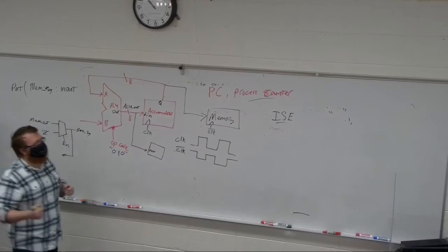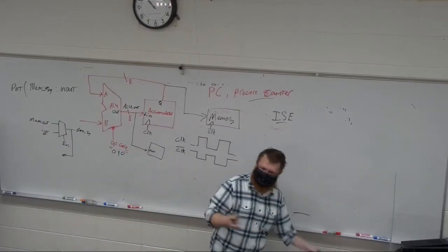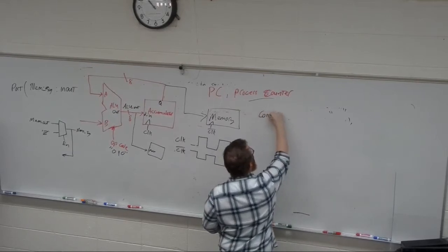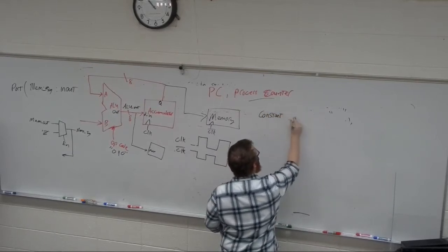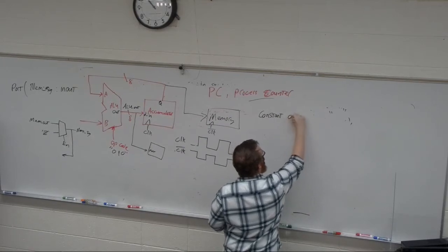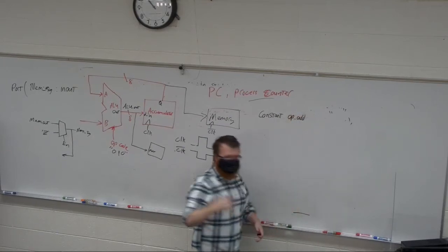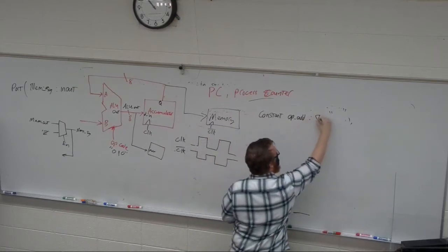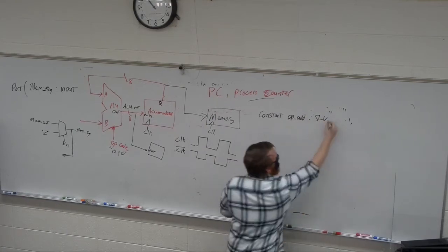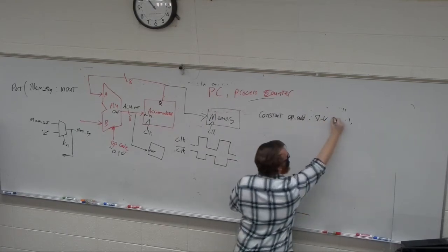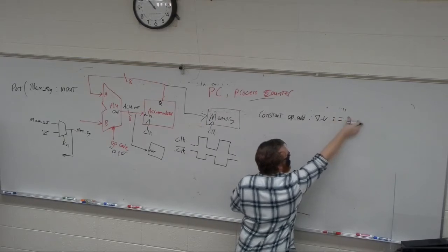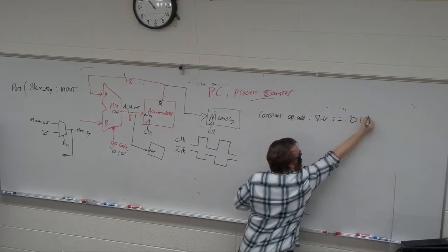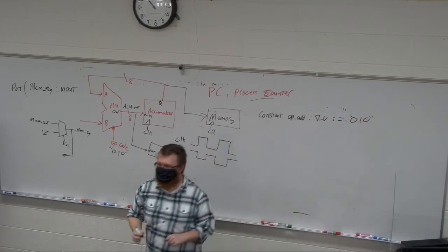So instead of declaring a signal like we have, you can actually say something like constant op_add, so my operation add, is the std_logic_vector that gets initialized to 0, 1, 0.